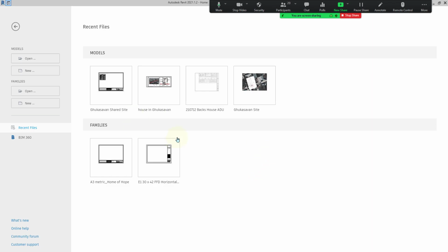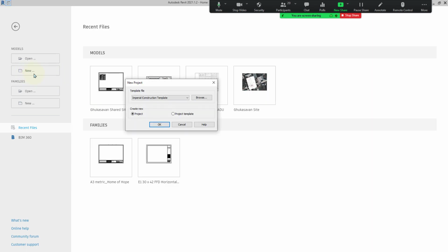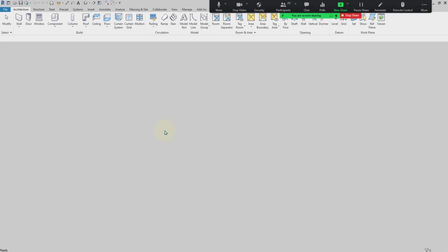Okay, so this video is going to cover kind of an intro to Revit and how to get started quickly. I'm going to create a new file. So when you open up Revit, this is the splash screen you get. I'm going to go to New. I'm going to go down to Imperial Architecture for this project.